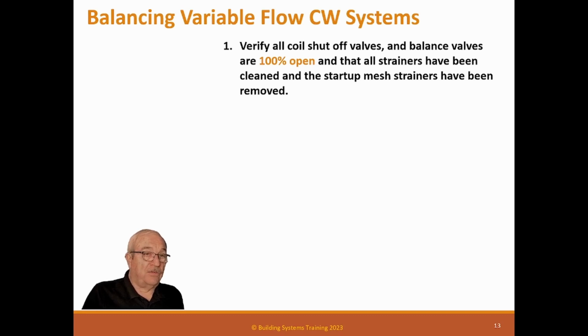Verify all coil shutoff valves and balance valves are 100% open. Now, it's pretty easy to tell if the shutoff valves are open or closed, but you need to check the balance valves because if they're not open, it'll mess you up. And all the strainers have been cleaned and the startup mesh strainers have been removed.